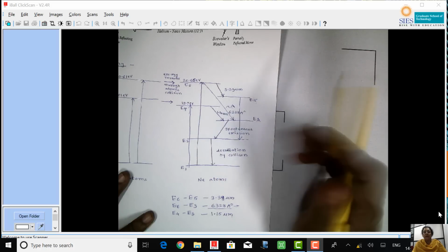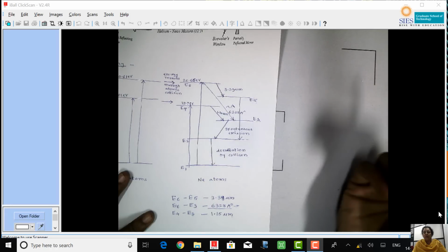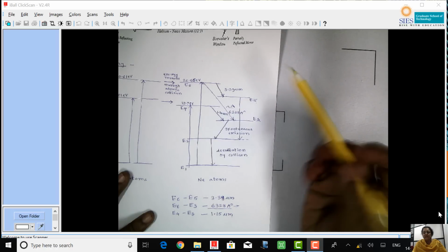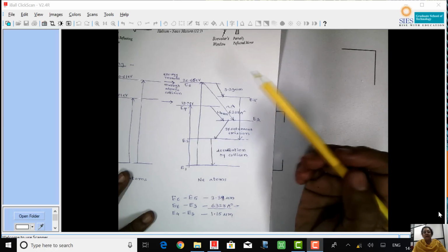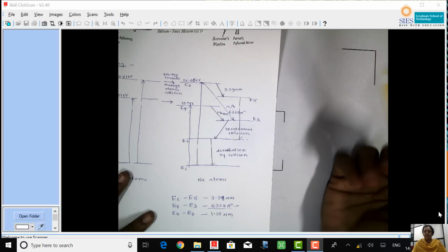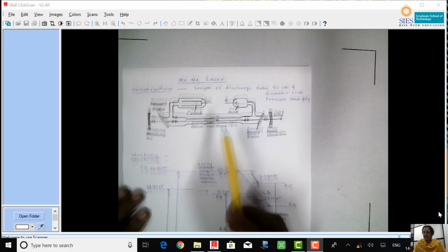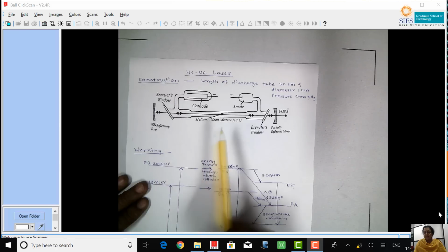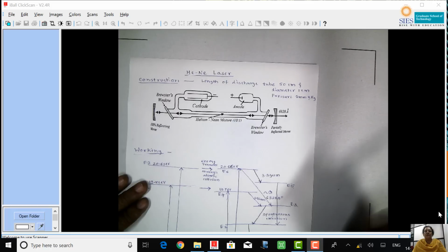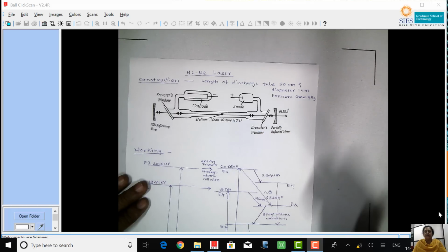So there is no drawback of light given out in the form of pulses. You will get continuous light. The only thing is that it requires a high tension battery, a powerful power supply, and the laser source is comparatively heavy. You will find there is a little time lag between the moment you switch on the laser source and the moment light comes out.